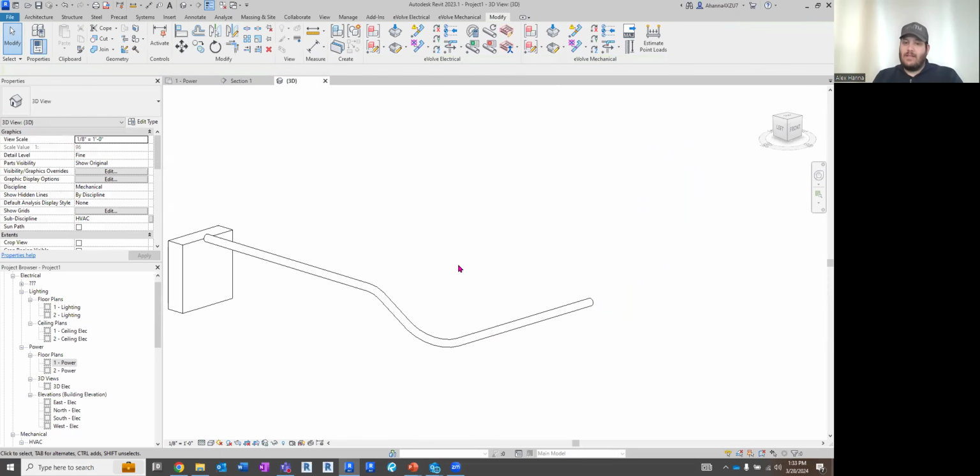So Revit is doing a lot of the process for you as far as putting that bend in, rotating the 90, so it's 45 degrees or 30 degrees. But the fact is that there's a lot of guesstimation with it. The beauty of Evolve on top of whatever I just showed you is Evolve has all these offsets as pre-made families. So just like I connected a conduit to another conduit using a corner command or placed a fitting inside of my model, you just place that offset in your model.